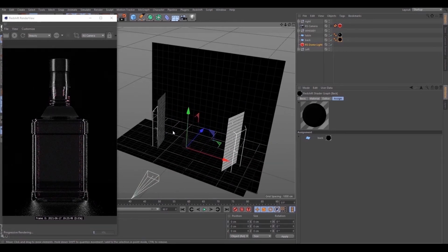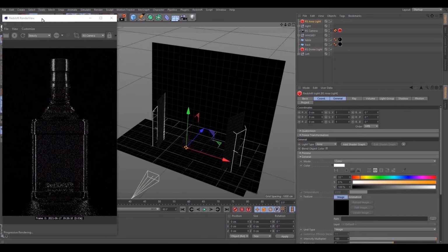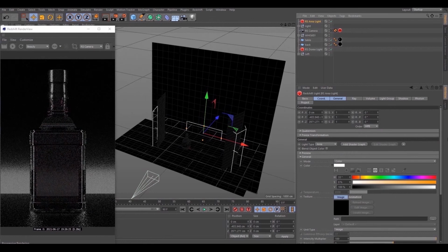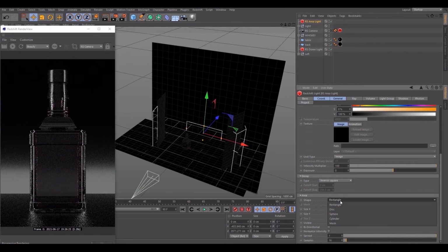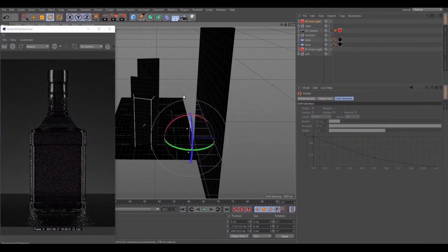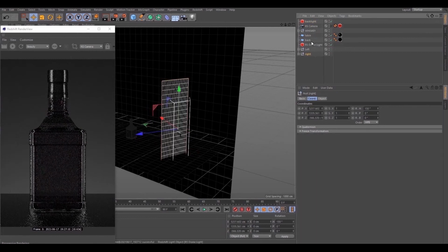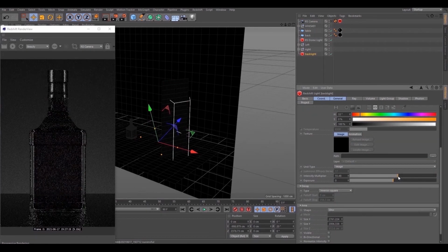Next thing, you can make a backlight on the wall to give some color shining. Create a new area light and place it back. You can change shape here, choose disk for example, to have round light. Rename, change intensity, size.